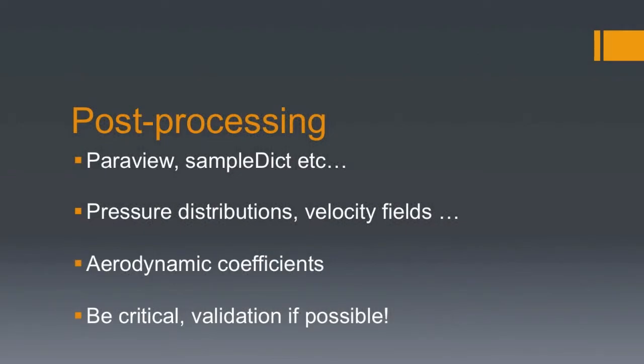Post-processing can be done with various software. ParaView is used to visualize this particular case. In aerodynamics, the most important results are pressure distributions and velocity fields. Aerodynamic coefficients such as lift coefficient and drag coefficient can be calculated directly with OpenFOAM.